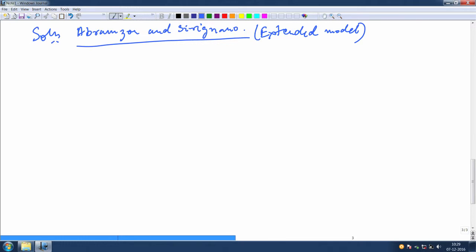So, we gave you the idea of what the gas phase is, what the liquid phase is and what the outcomes are, but let us just give you an idea of how this whole thing is solved. The first step that people do is calculate, and this is solved numerically. I am just giving the algorithmic steps, from the gas phase perspective: calculate the molar and the mass fraction of fuel vapor.